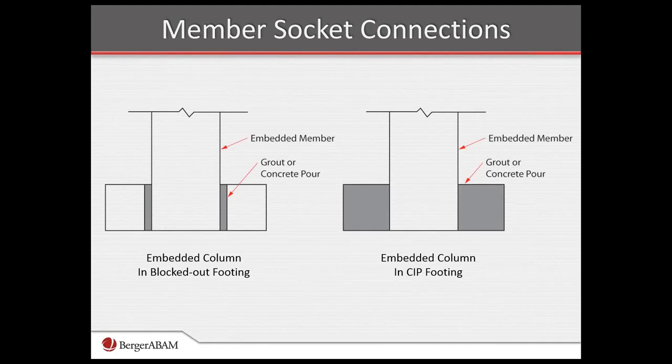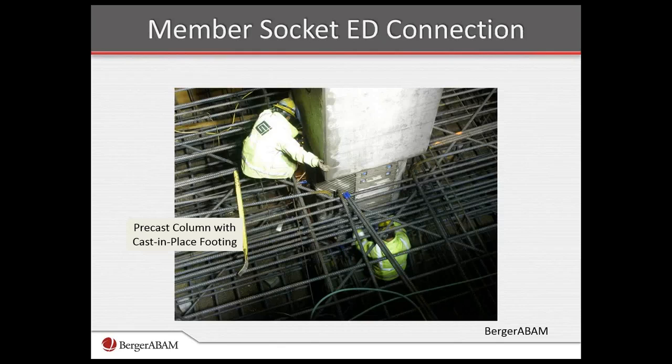Shown here, two different types. One is a socket with a member that goes into, say, a cast-in-place footing. The other on the left is you could have a precast footing with a block out that then is grouted up. So the one on the right, again, has been tested and deployed. The one on the left has actually been deployed but not tested. So it's an idea. It works. It's worked when we've used it in the past, but it's not something that we can point to a lot of laboratory data on.